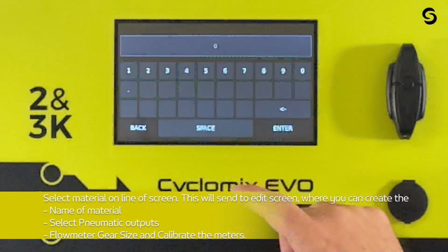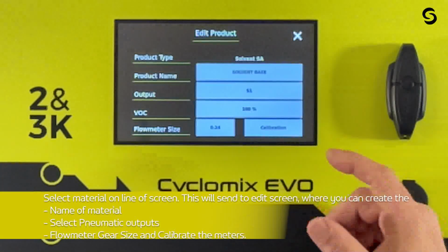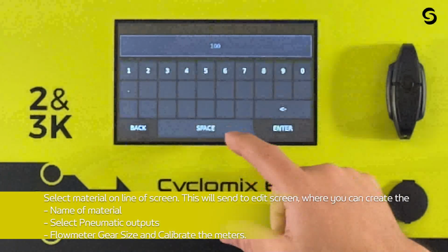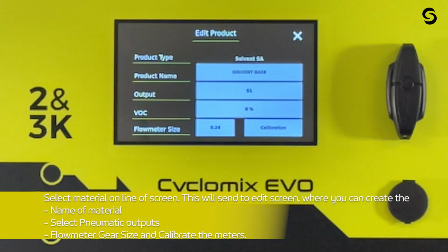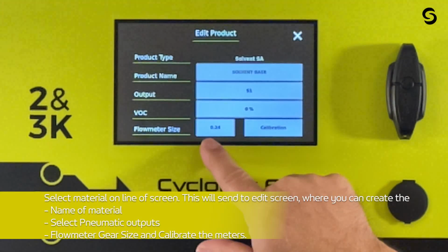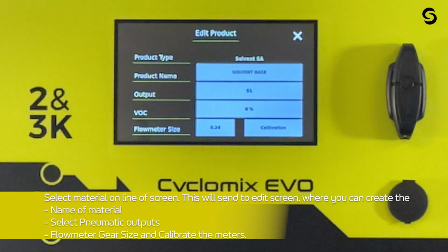Now my VOCs, depending on what solvent, could be anywhere from 100% to, for some of the more volatile solvents, or if I'm using an exempt solvent, it could be 0. Or in one case, if I'm using water to flush. We have flow meter size. The standard setup is going to be 0.24, but I can actually go in and calibrate and fine tune this.